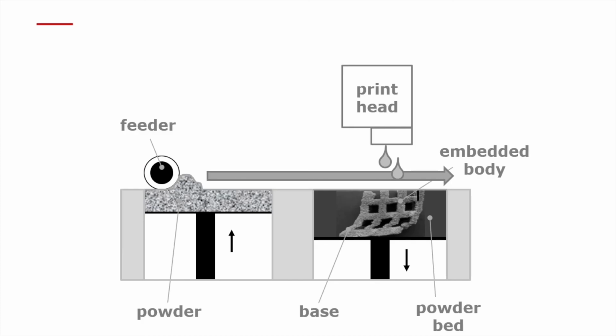The gas flow assisted powder deposition process was envisioned to stabilize parts in the 3D printing process. Why is this necessary? I said the powder supports the part in the powder bed, but the powder is rather loose, and when we print our standard ceramics, bioceramics, coarse-grained powders in a fraction from 60 micron to 100 microns, then we get a packing density typically of 40%, so the powder bed is not very tough.